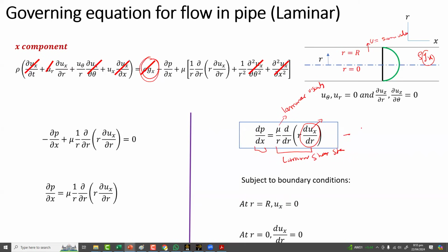If we have another term, mu t, with a similar derivative of velocity with respect to y, that is the turbulence part. To find this turbulence, we need two equations, k and epsilon. They came up with the idea that if you can find k and epsilon, some ratio of k and epsilon will be equal to mu t. So now we have this laminar viscosity and this turbulent viscosity. Whenever pipe flow has turbulent effects,